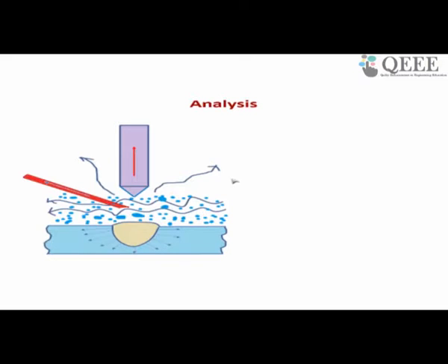Then we discussed high density welding processes. We discussed electron beam welding, where the thickness to diameter ratio will be very high. You can even join very thick material. If the ratio is 25:1, you can still join two materials using electron beam welding. And there we discussed that in electron beam welding, the power density is very high. We also discussed how to classify all the welding processes based on power density.